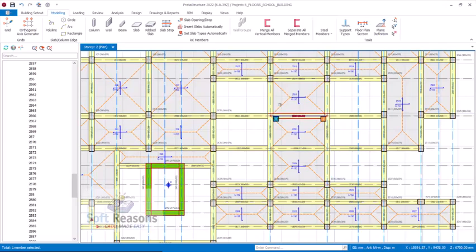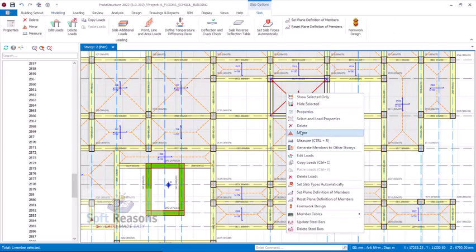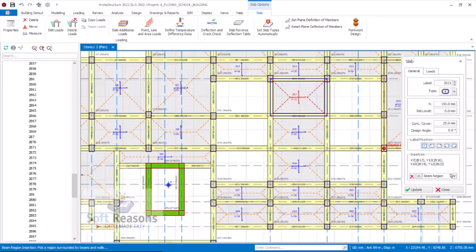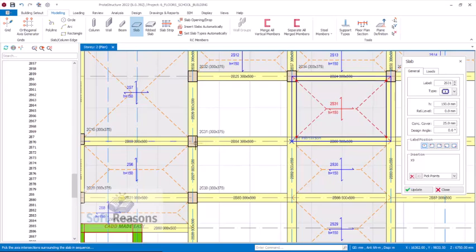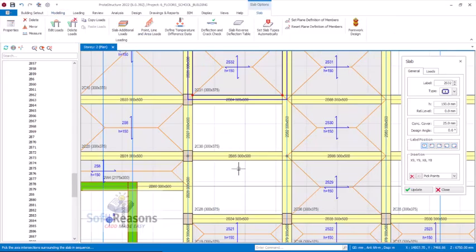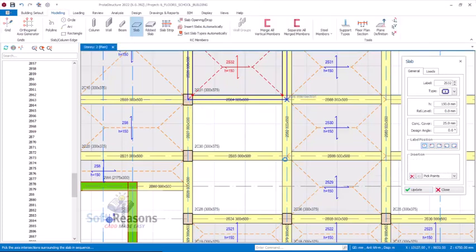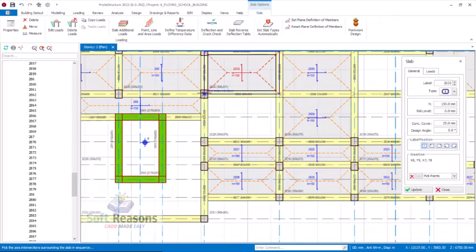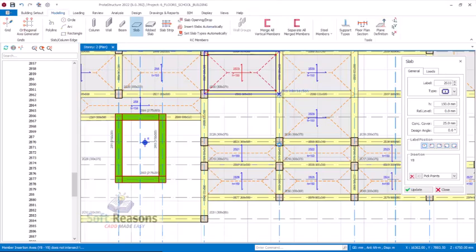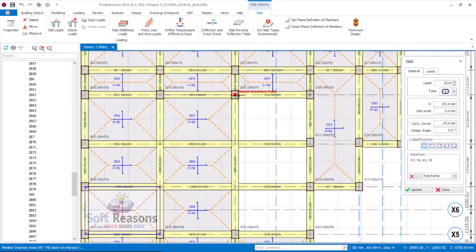Okay, at this point we will use pick point. So select one of these, right click and click on its properties, after which come to this provision, use pick point options, clear here. So you can pick the first point, second point, third point, fourth point to have it placed just like that. Clear here first. The same thing applies here.